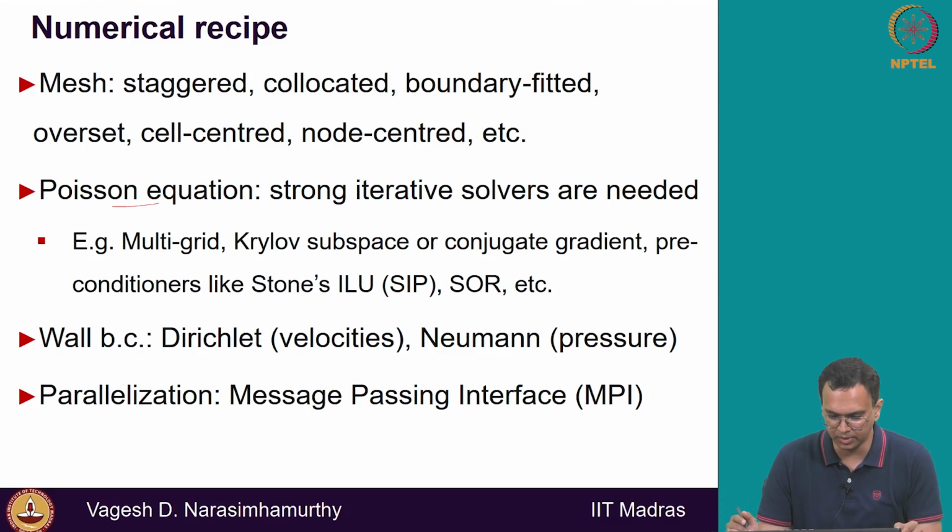What is the computing power required? The boundary conditions are easier here. You're only solving for 3 velocity components, 1 pressure, right? So pressure is set Neumann, velocity is its Dirichlet conditions, like you have no slip and kinematic boundary condition. You don't have to worry about boundary condition, it is straightforward.